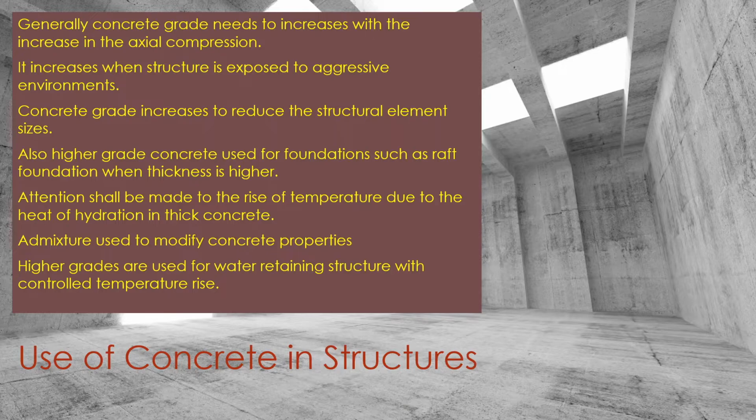Higher grades are used in water retaining structures with controlled temperature rise. We have to control the temperature rise: when the concrete grade increases, the heat of hydration increases. Therefore, we have to control that.